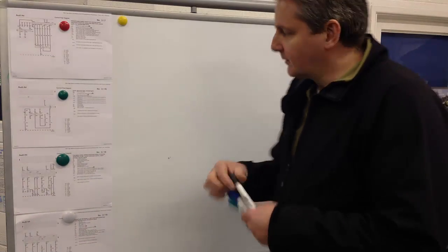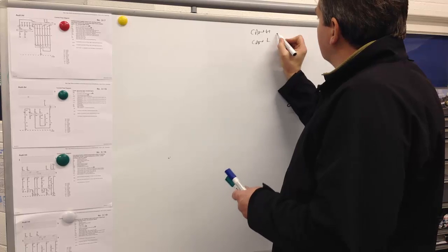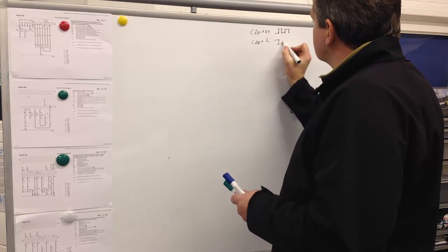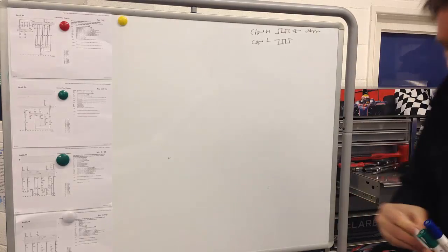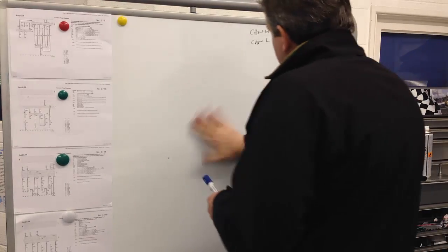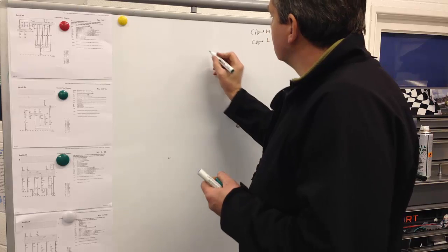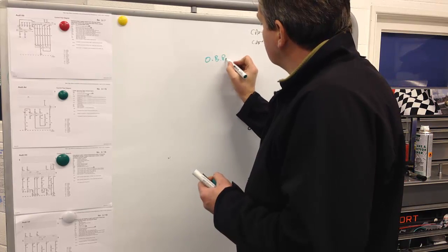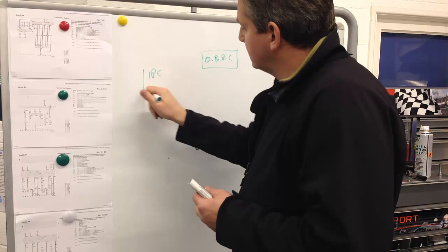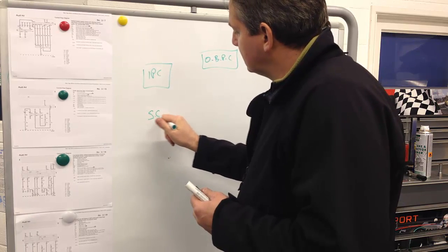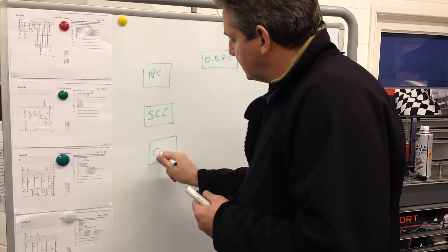When we think about the fault that we've got, two signals essentially on our network. We've got CAN high and CAN low, and CAN high is our signal that goes up, and CAN low is our signal that goes down. We've got an issue on our high, and our high is looking like it's very much disrupted. When we consider the way that the diagram's showing us the way it's connected, we've got several modules. We've got our onboard power control unit there. We've also then got our instrument panel. We've also got our steering column control unit, and we have finally, last but not least, our central convenience.